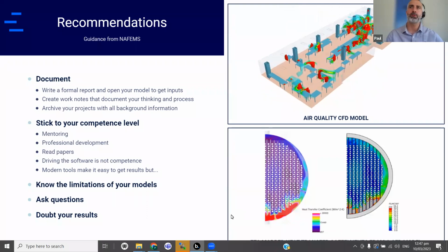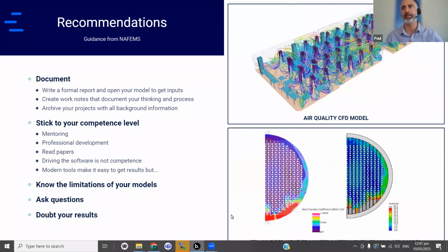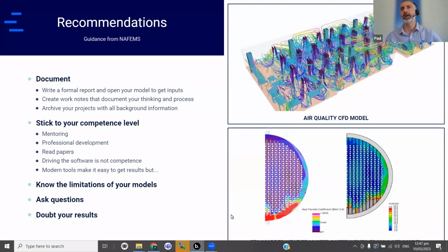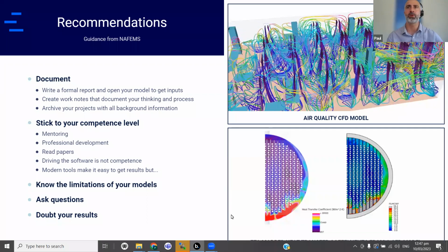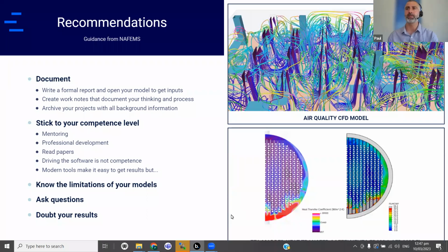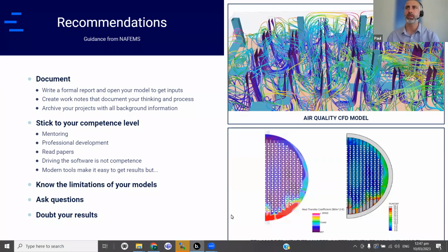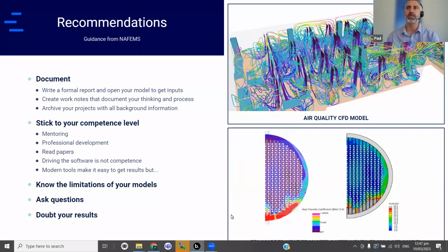Another example, typical things, in a pressure vessel, I always check the radius, because that's so fundamental, and the thickness. And maybe you want to check if there's a corrosion allowance, whether that's been included or not. Anywhere where you think there is some uncertainty in a data point. Material data is another area where sensitivity is often checked.